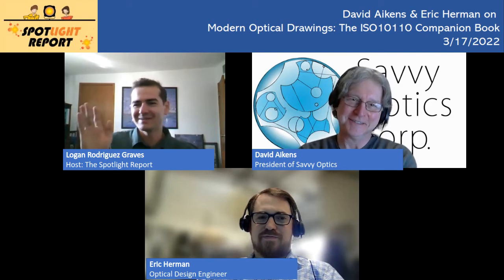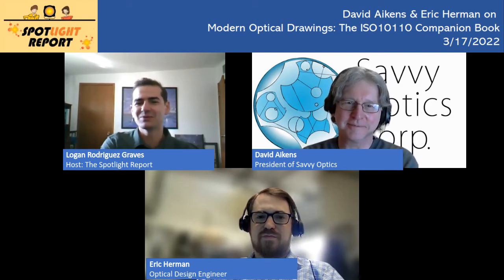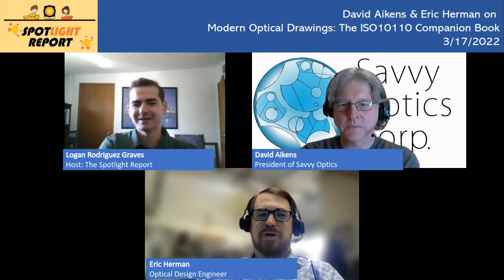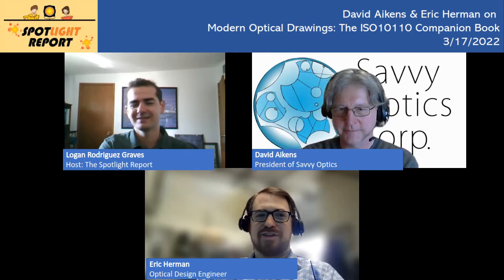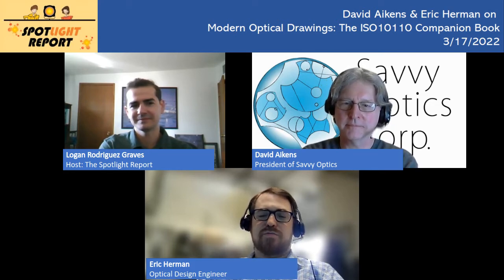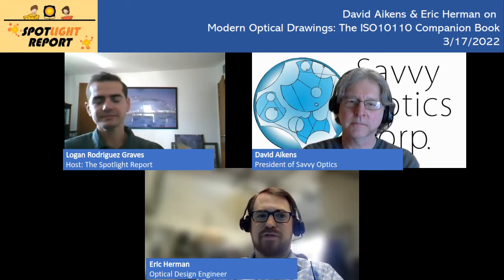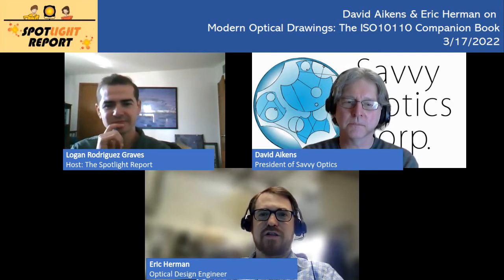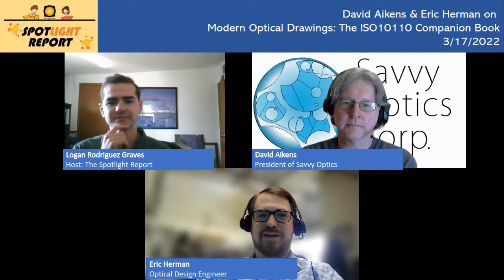It's right. It's 1.5, refractive index, whatever. I'm good. So why would I spec out optical material parameters? Because with, say, Schott BK7, you're not always going to get exactly what you think. There's always going to be some deviation from what they're going to make, and that's more than just batch to batch. If they're making strip glass, one part of the strip might be very different from another. So setting those tolerances is making sure that you're at least getting what's good enough for the Schott BK7.